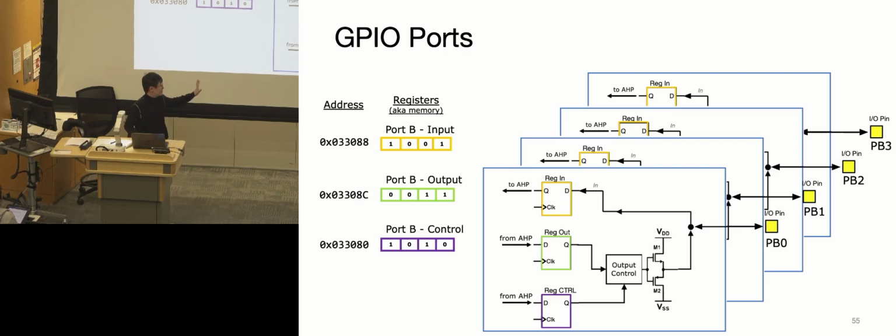And these are determined later on. We would iterate on this based on the P address within a peripheral. This is a case where you have multiple registers within a peripheral, so on top of the P enable and P select signals, you also need a P address to know exactly which register inside of these peripherals you need to access, write to, or read from.